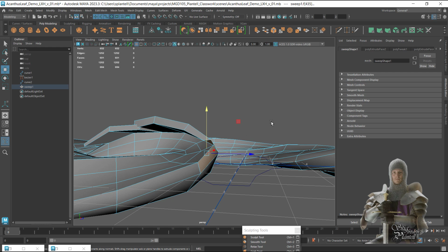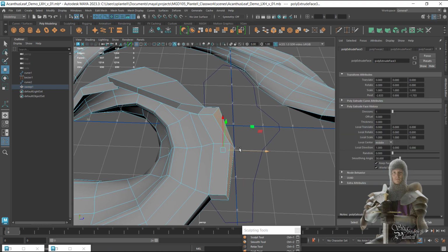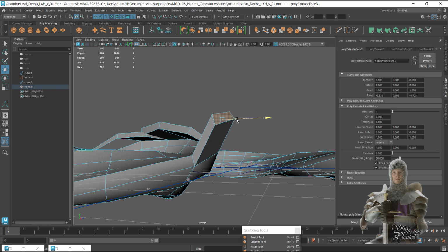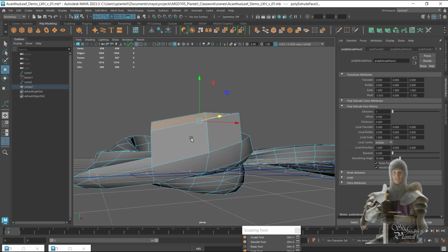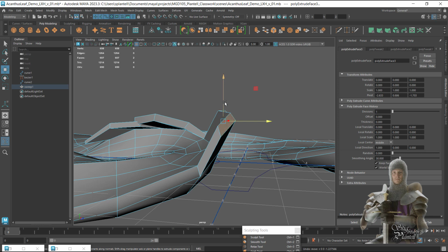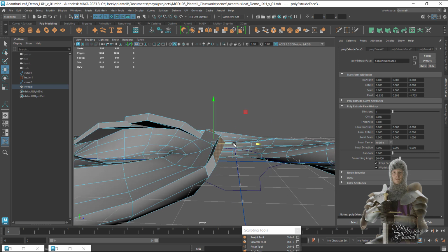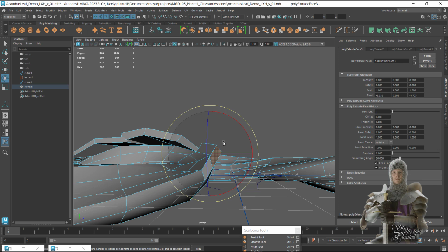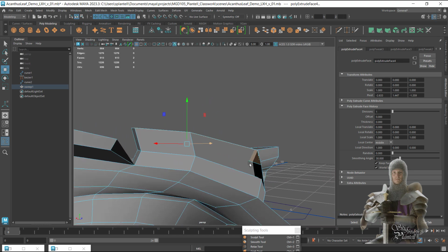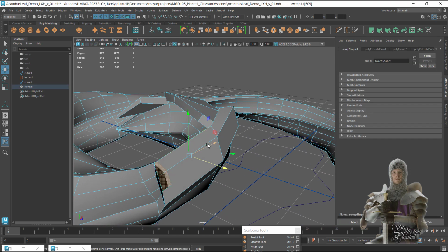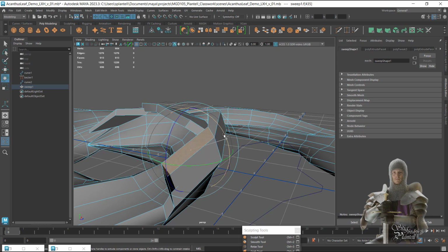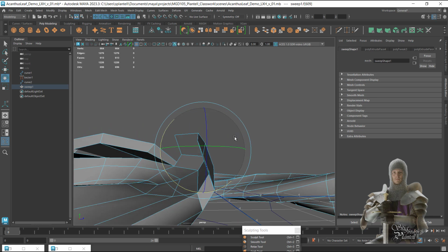I'm going to hit the extrude tool. No, I'm just going to do it with this shift. I'm trying to make it fast and successful for you. Now you can also go in there and do a couple steps. I could go to make sure this thing wraps over. I could roll this and go another extrusion. And bring that over so it starts folding. This face here needs to be rolled over. Let's do it with the